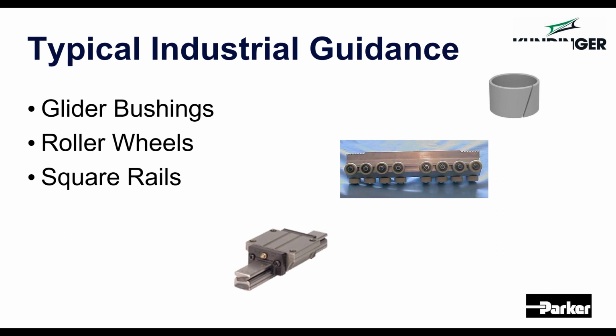And because we use belts like that, sometimes people are always afraid of belts are going to break, things like that. We have never, in the 20 plus years we've been manufacturing belt drives, we have never had a belt break. So these things are great for long strokes. We make some actuators that'll go to 10 plus meters using belts, high speeds as well. They're pretty low cost for the kind of performance you can get out of them. And you can still get an incredible amount of thrust force out of belts like this.